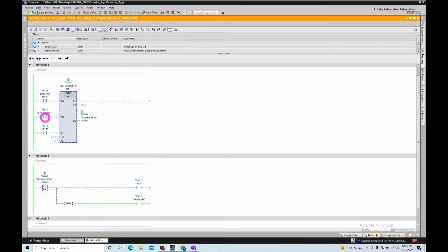In the CD, I put the exit sensor. Again, whenever any car goes out of the parking lot, the sensor produces a pulse. I simulate this sensor's job with a toggle switch, which I connected to input 1. If I toggle the switch at input 0, it means the sensor sends one car. Here if I toggle this sensor, it means the output sensor or exit sensor sends a passing car. I don't use the LD, I just put false all the time.